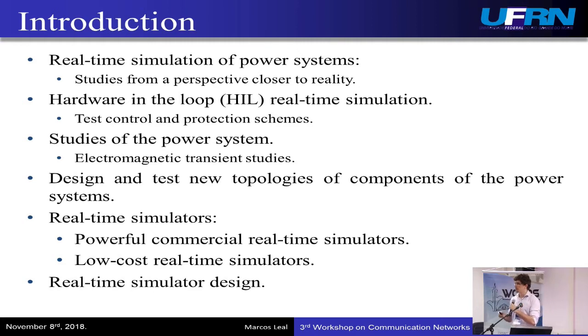They have powerful computation, and you can model larger power systems using them. And there are low-cost real-time simulators. If you don't need to model larger power systems, you can use a low-cost real-time simulator, or you can design your own real-time simulator. And you will have more flexibility to perform your simulation, like choosing your time step according to your application.